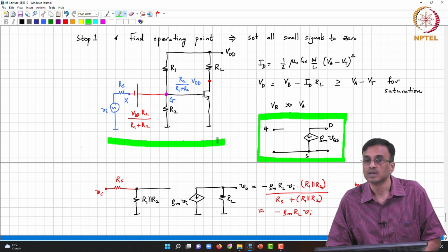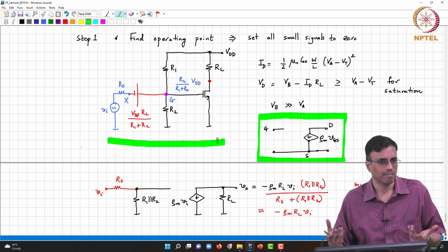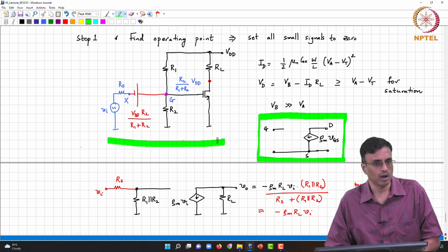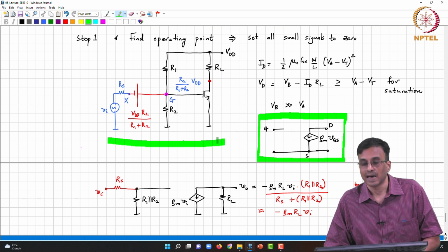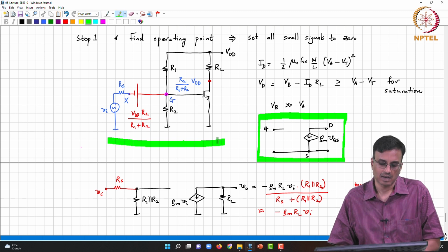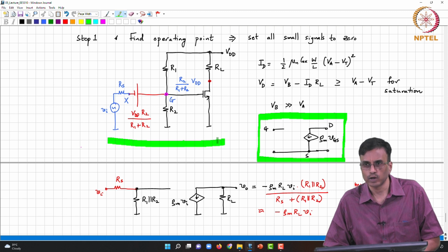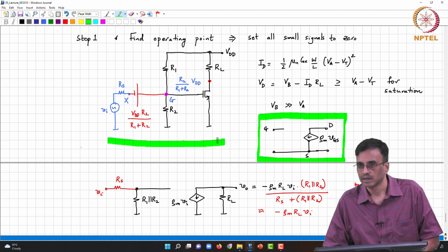Zero. Why? The two potentials are the same. So, there is no current being drawn from the battery. Okay, and remember we also talked about how to realize a battery with a capacitor. What did we say? An infinite capacitor charged to a certain voltage is equivalent to a battery charged to the same voltage, and in this particular case, even if that infinite capacitor is replaced by a finite one, notice that there is no DC current going through the battery, correct.